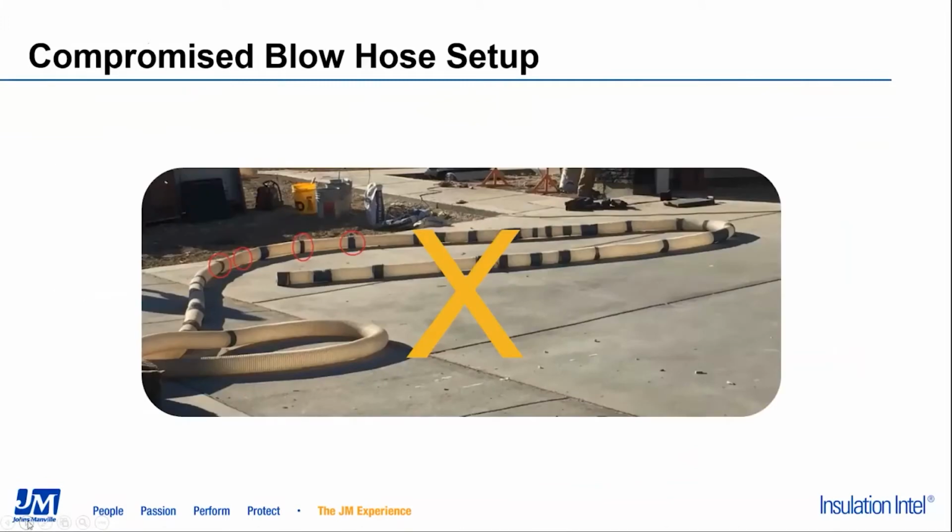We also want to make sure our hose is in good operating order. Hoses like the one that was shown here are worn out. The small ridges that help tumble and process the glass are worn away. This will negatively affect your yield. Also, the sidewalls in a hose like this are very thin. The back pressure from the cavity fill can cause the sections to blow out, wasting material and creating messes that you'll have to clean up later.